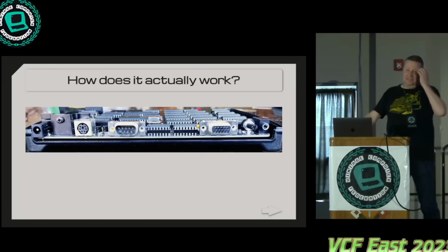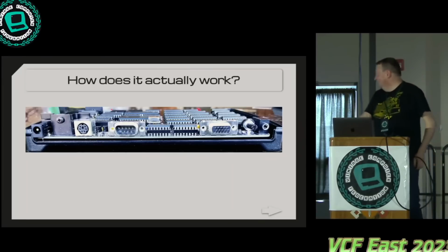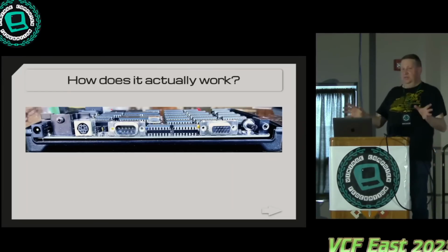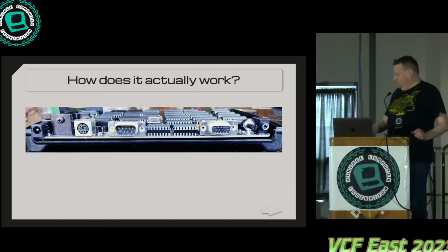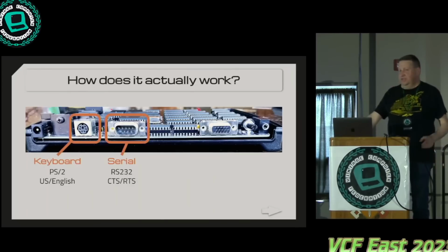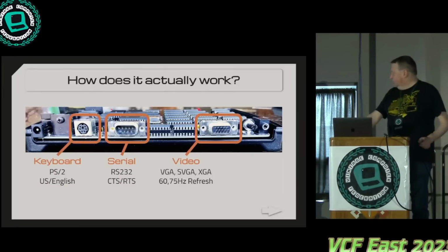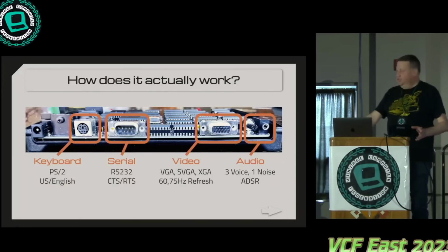So how does it actually work? So yeah, that's the CPU. It's super basic. We've got the keyboard interface, serial interface. There's no UART. There's no video chip, no VIC or SID chips or anything like this. So all of this has to be bit banged.